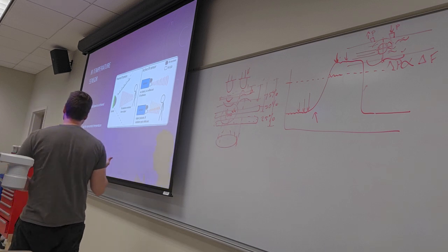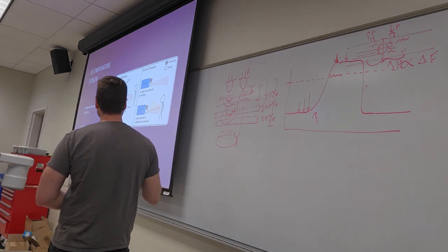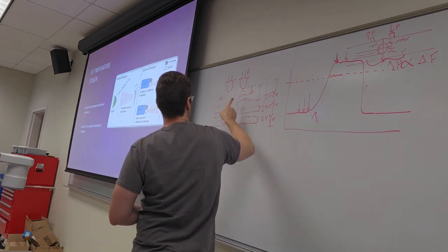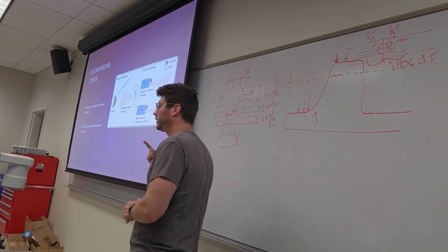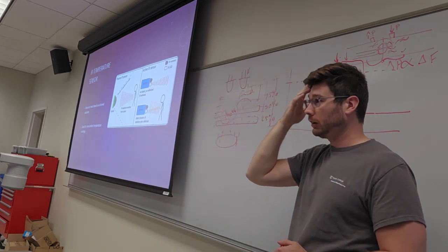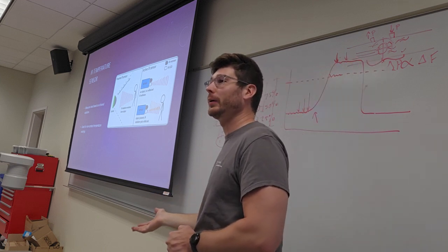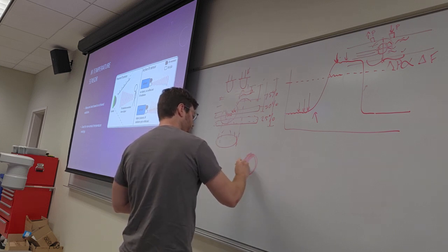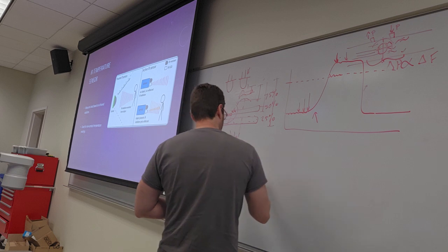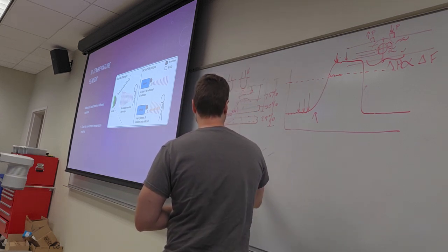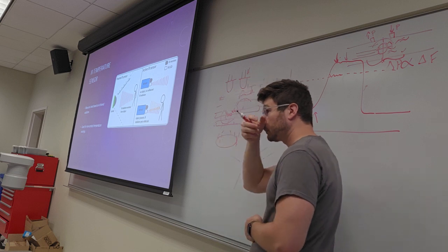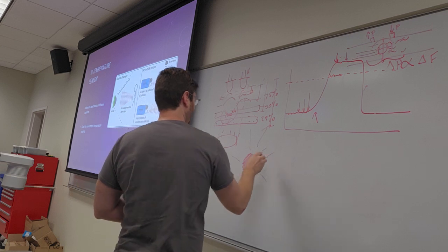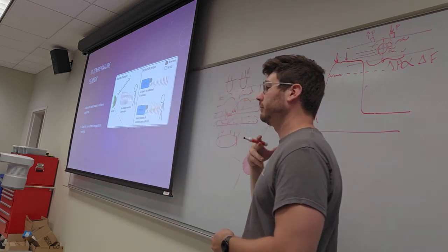IR sensors can be used in two different ways, essentially. Well, many different ways, but one of which is without this sending element. If we just have the receiving element, that's how we get things like IR temperature guns, right? That check how much light is being emitted by your forehead in the IR band. If you guys didn't know, it's something called black body radiation. If something was in the middle of space, it would still give out photons if it had some amount of heat to it in the IR band. This is effectively what this IR sensor is reading all the time. It only cares about the photons that are given off as heat.